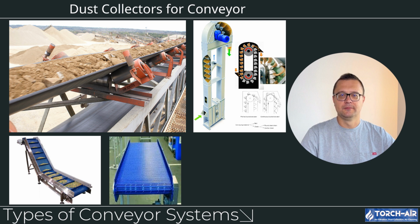Bucket elevators. Common in vertical transport. These conveyors can generate dust during bucket filling and discharge. Drag chain conveyors. Used for heavier materials, dust can escape where materials are dumped in or out of the conveyor. Each conveyor type creates dust in specific areas, so understanding the dust-generating points is key to controlling emissions effectively.